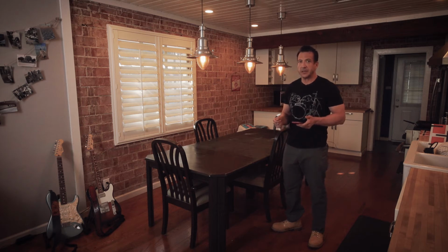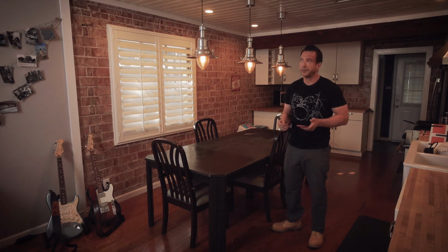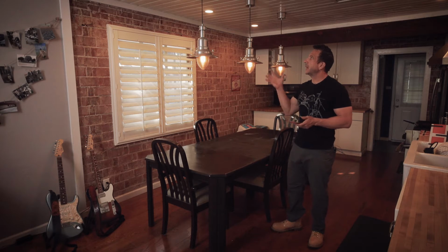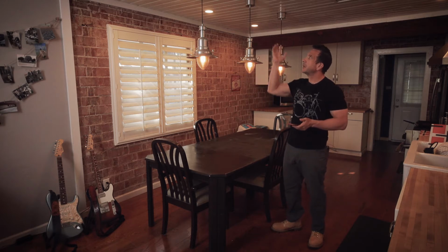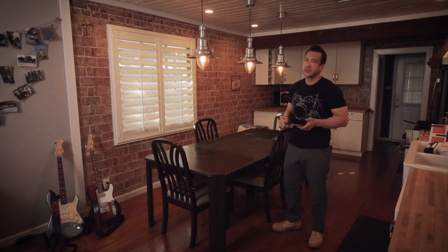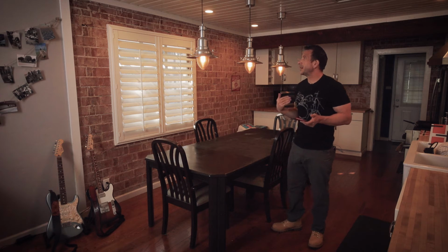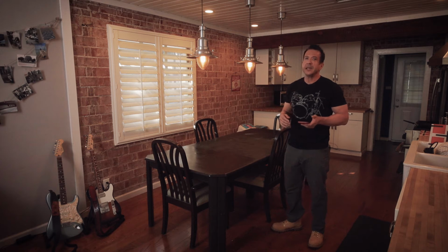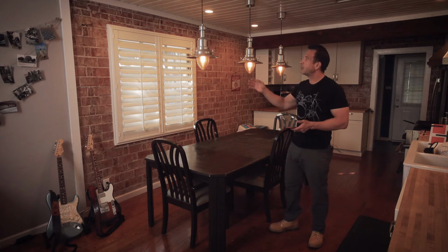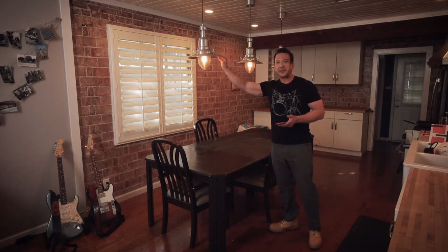That really allows you to minimize the penetrations associated with the light fixture and to help mitigate some of that acoustic control. And so having a light down in the space and having a minimal penetration is probably going to give you better results in terms of acoustic control. But obviously in my space, as you've seen in some of the other videos, I'm sacrificing some headroom in order to build a separated ceiling. So the last thing I want is any sort of pendant type, just the idea of ending up whacking my head on the thing.